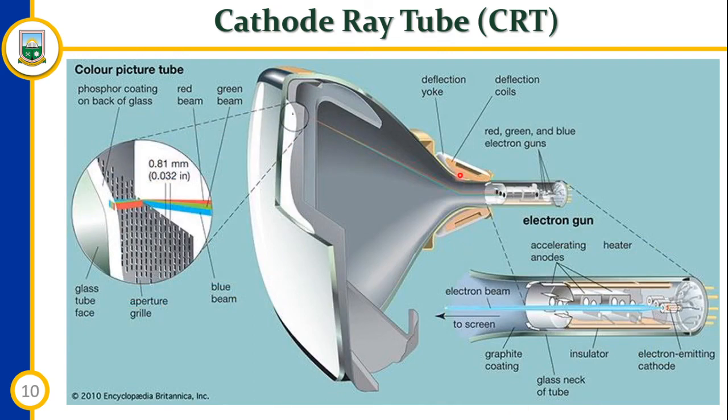So, just as I've said, we have the electron gun consisting of a series of elements, primarily heating up the filament at the back and the cathode. So now the electron gun creates a source of electrons which are focused into a narrow beam directed at the face of the cathode ray tube. We also have a control electrode which is used to turn the electron beam on and off.